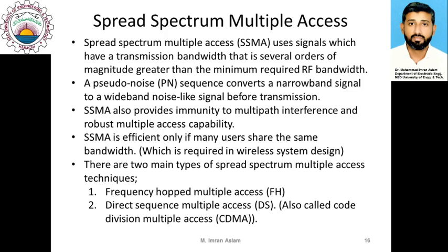Let us now move on to the third multiple access technique, which is the spread spectrum multiple access technique. This is actually the same as the spread spectrum modulation system that we discussed in our previous week's discussion. In spread spectrum multiple access, a single user's signal is spread in the frequency domain.